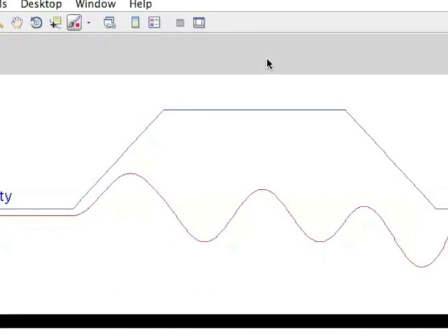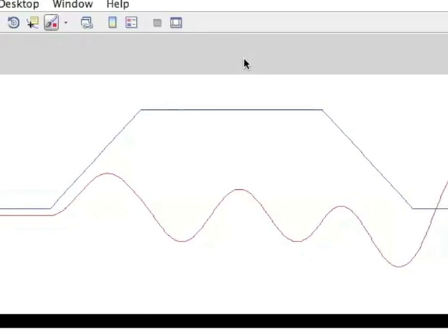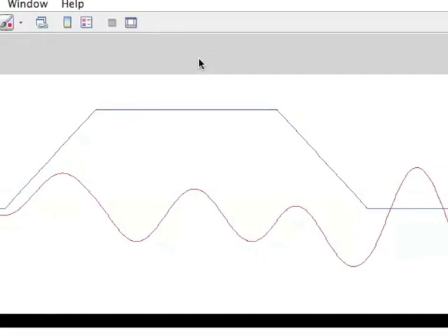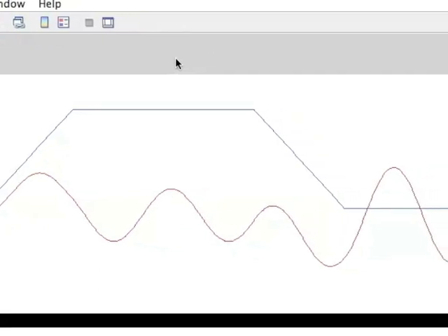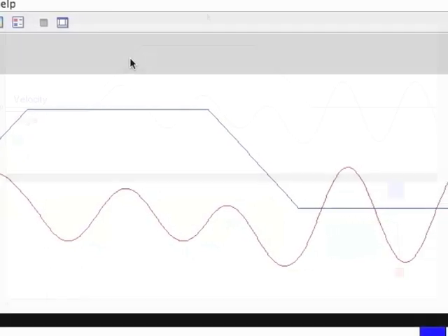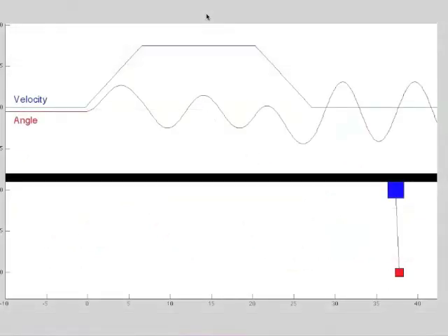It continues throughout the constant velocity segment and seems to be exacerbated by the stopping of the trolley. So having tcoast equal to 10 seconds and txl equal to 5 seconds does move the trolley 37 meters. But the problem is we have a lot of swinging at the end.